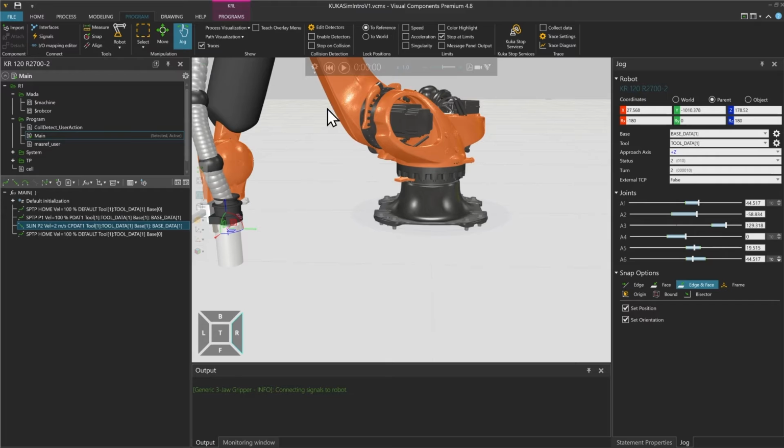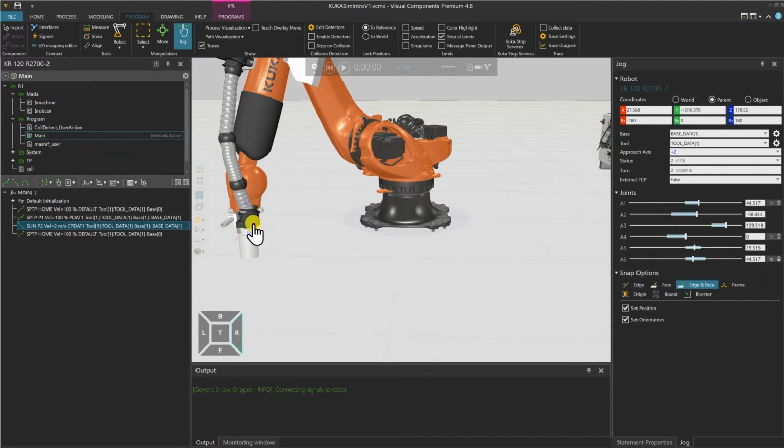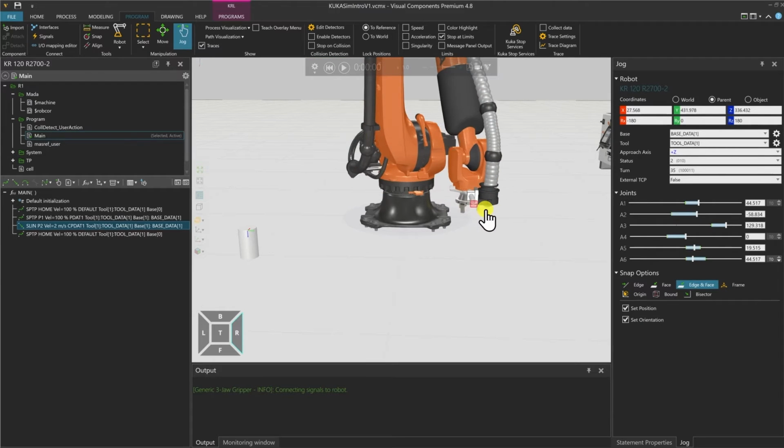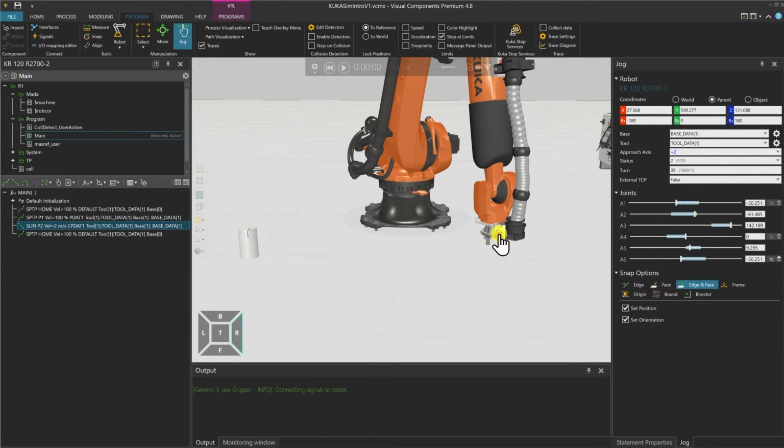The last thing I want to do is to showcase you the circular movement. So I want the robot to go all the way here with a circular motion. So I'm just going to click on this circ motion. And it actually creates 2 points, so the point 3 and the point 4. If we have a look at the frames of the robot, it created a third point, the point 3 here. And the point 4 is my endpoint.